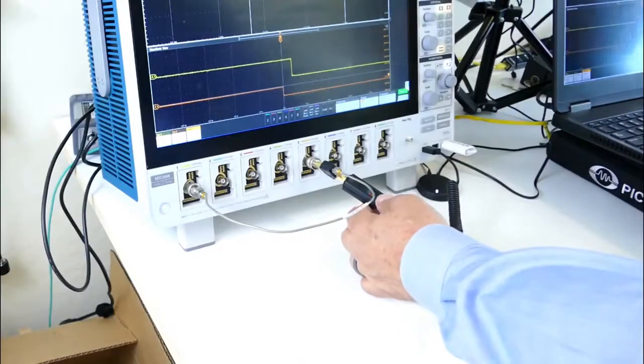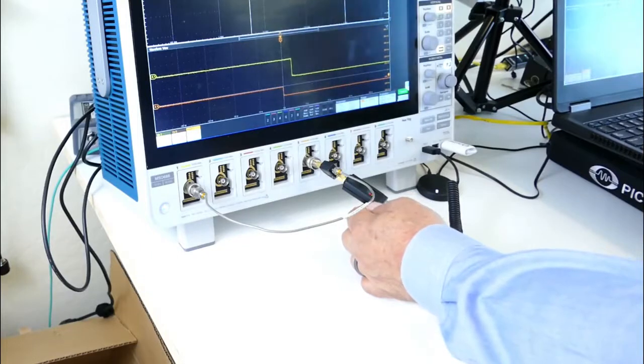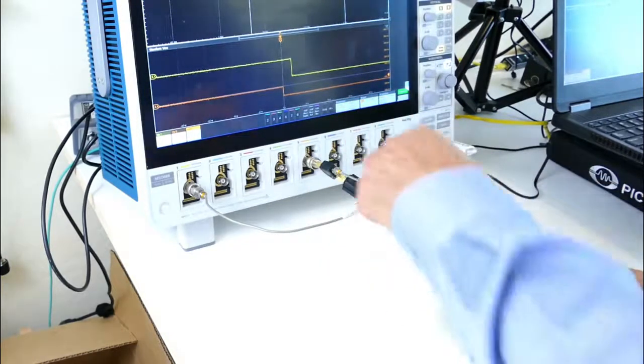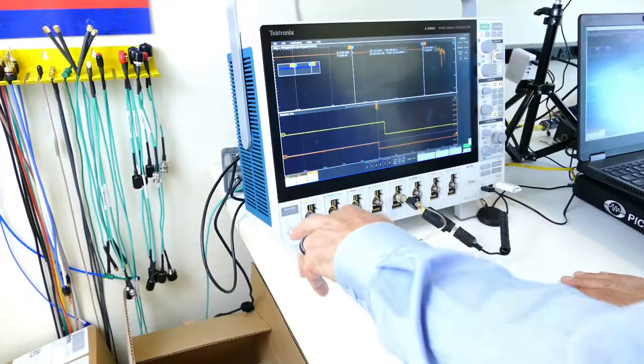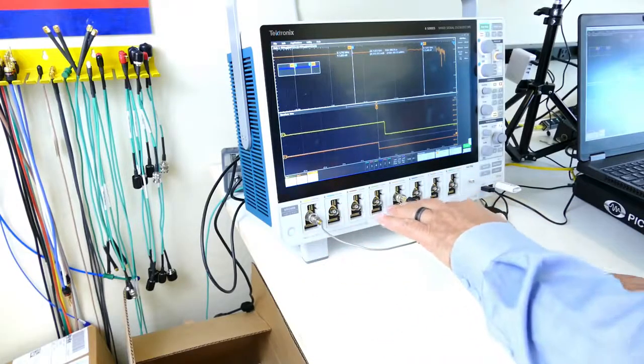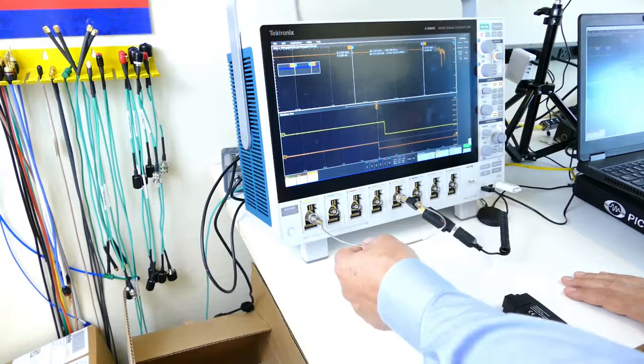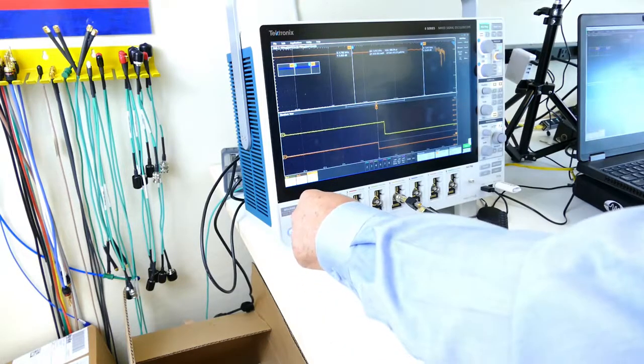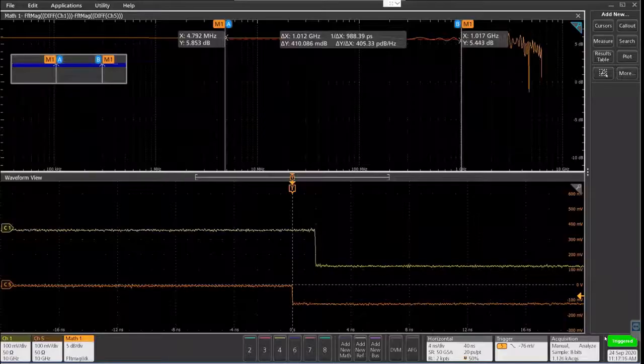The signal generator here is a 32 picosecond edge, so about a 10 gigahertz bandwidth, and it goes through a power divider here. And in this particular measurement, we're measuring the bandwidth of really a flat wire. And so it's this RG405 rigid coax and the BNC connectors on the end. And you can see that's pretty flat. And so that's what we expect.